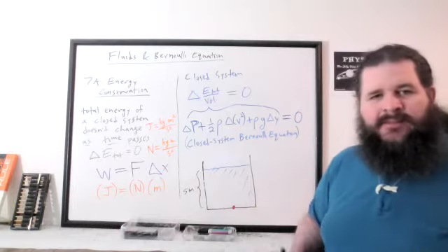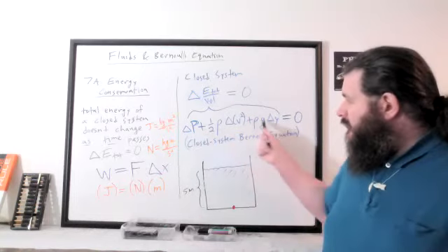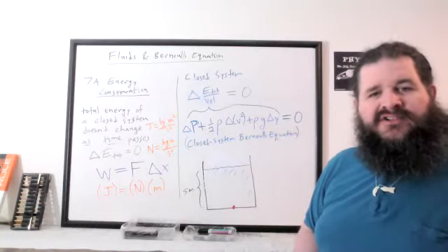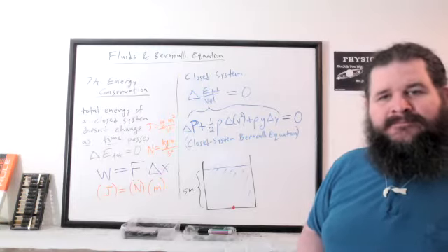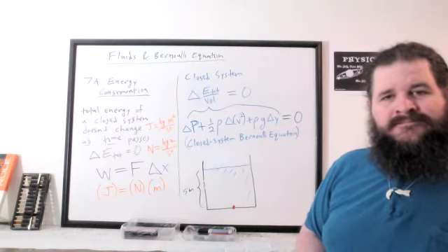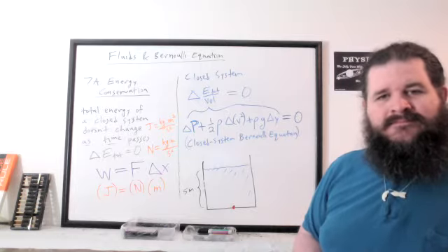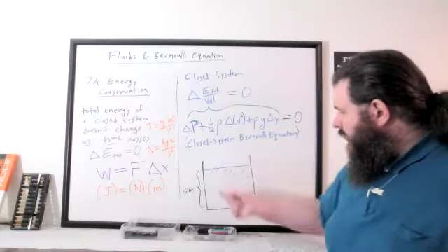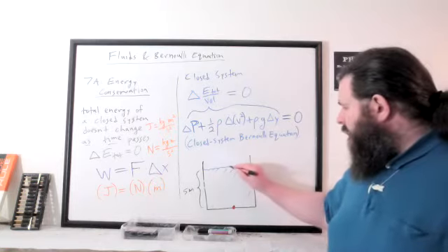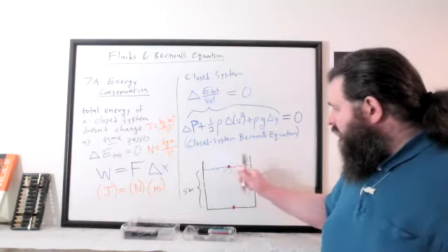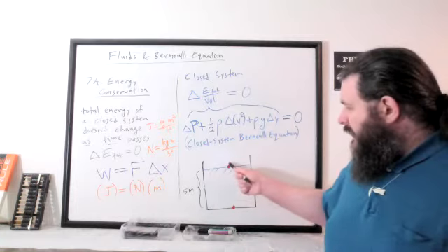If you want to find the pressure at the bottom, what's another location we could compare that to? Because the Bernoulli equation is all about comparisons with these deltas. So what's another good location to compare that to? Is there any location in this entire tank of water where we would know the pressure or where we might be able to find the pressure? At the top, yeah. And the top is very useful because the top is an interface between two fluid systems again. We've got an interface between the water and the air.